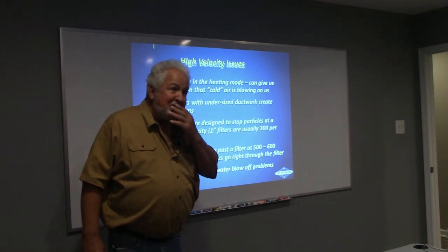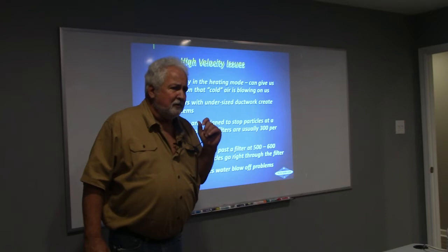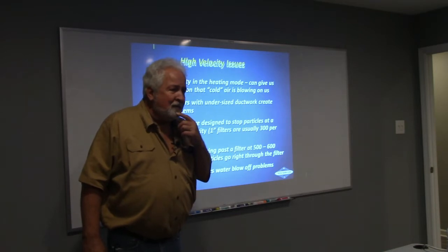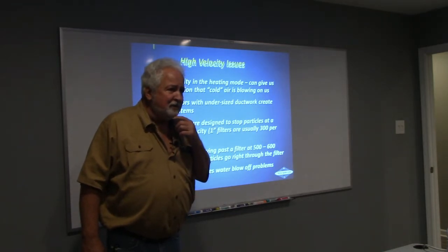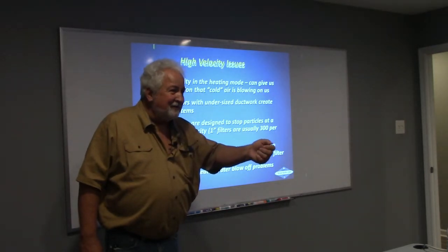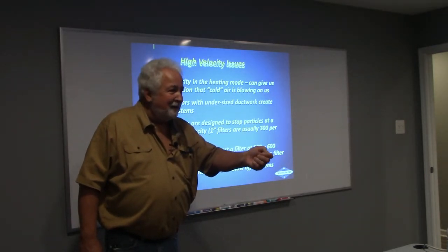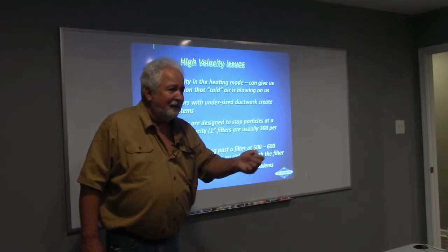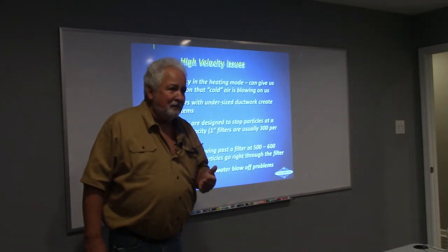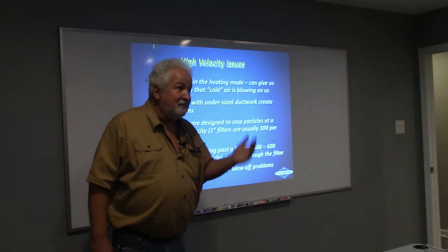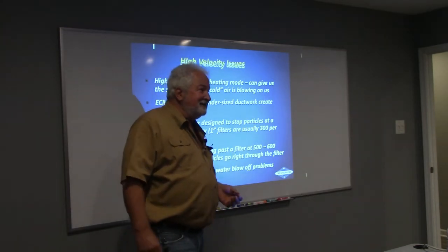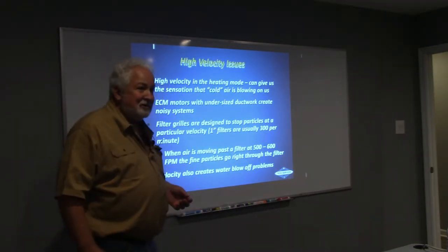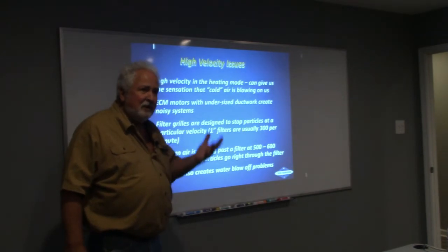That might be a problem for a couple of reasons. Listen to air moving through a big duct. Listen to air moving through a small duct. What are they having to do every time the air conditioner comes on with small ductwork? Crank up that television, is that right? Up and down and up and down and up and down. You seeing what we're talking about? What's killing the motor? We hadn't even gotten there yet. We're just talking about the problems that customer is going to hear right off the bat.